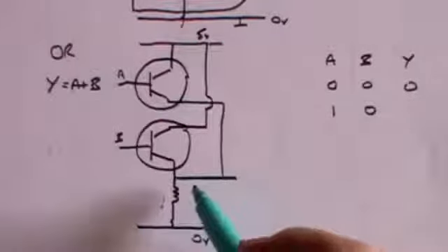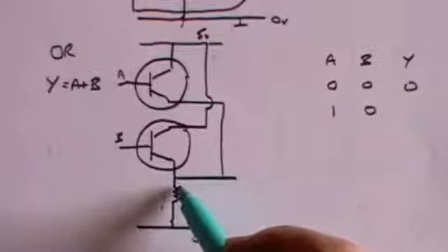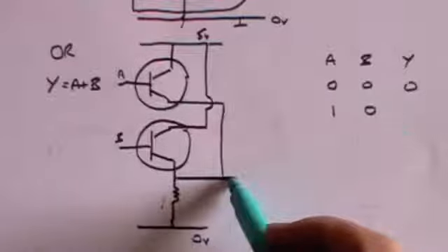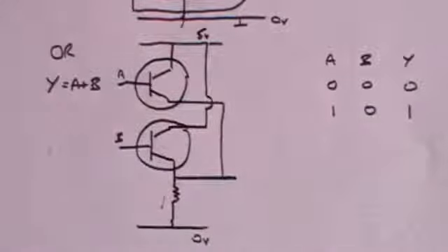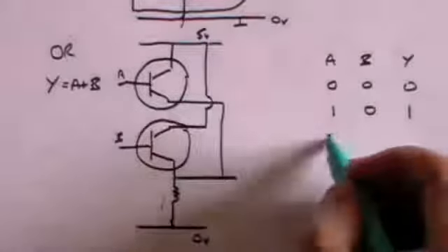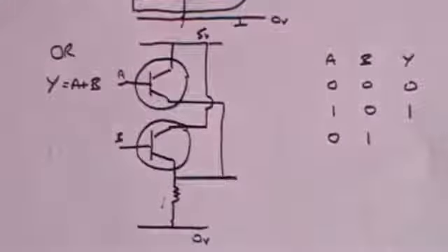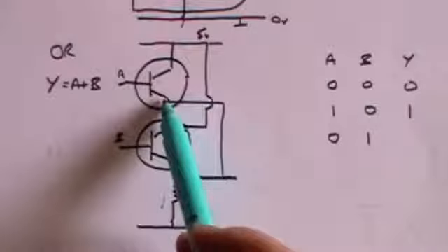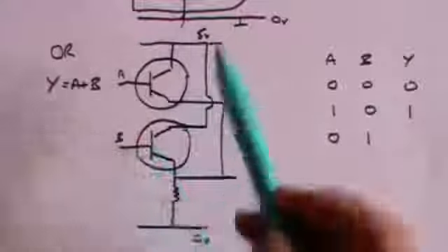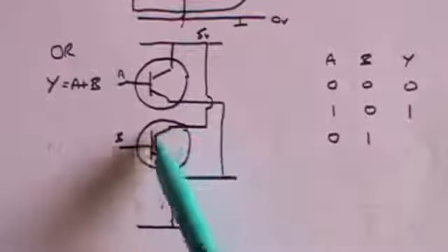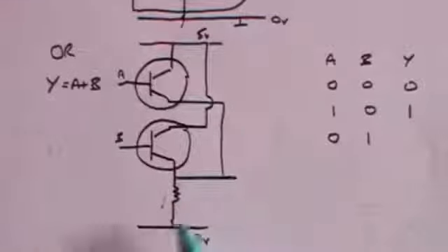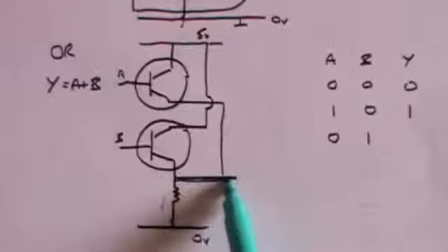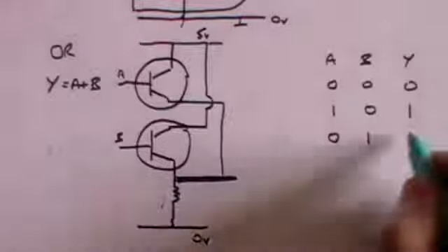And that means that there will be a potential drop across the resistance, but there'll be a positive voltage on the output. So there's a positive voltage there. And I think you can see fairly easily that the same is true if it's the reverse. If A now has no voltage, there'll be no current going that way. But if B has a positive voltage, then the current can flow through the transistor and down here. The potential is dropped across this resistance, which means that the output here has a positive voltage.